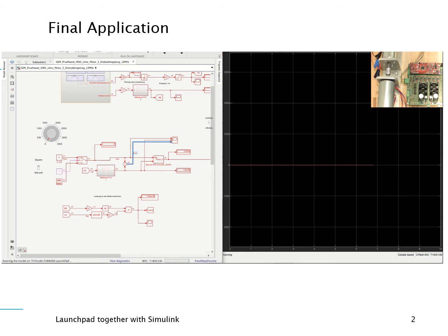Today we use just one of them, as well as the power electronic circuit and the Texas Instruments Launchpad with the USB connector to the computer. The communication now is running with Simulink to the target board with around about 9 megahertz or 9 megabit per second.